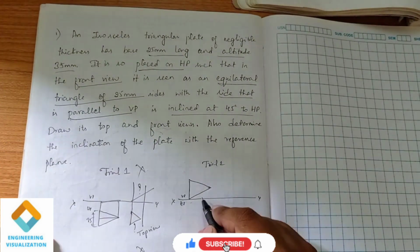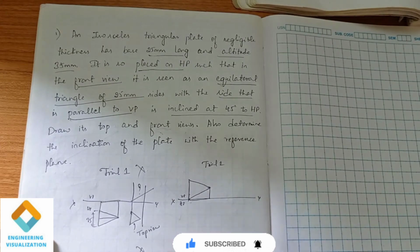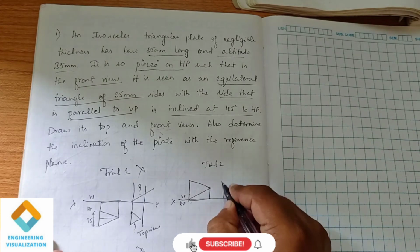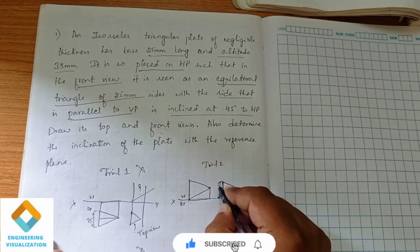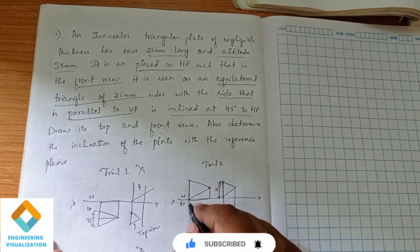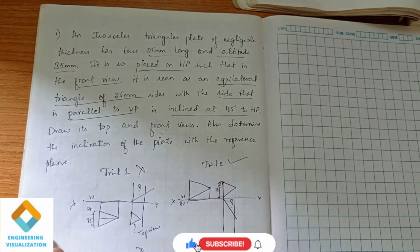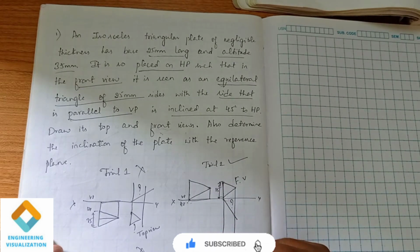Say this is the front view, then projecting downward we get the top view. Now in this position they have not mentioned the second angle of inclination, so we have to construct an equilateral triangle of dimension 25 here. Then by proceeding like this, by taking this length, we can find out the angle of inclination. So this trial 2 is correct, because you can see this is an equilateral triangle, so we are getting it in the front view.